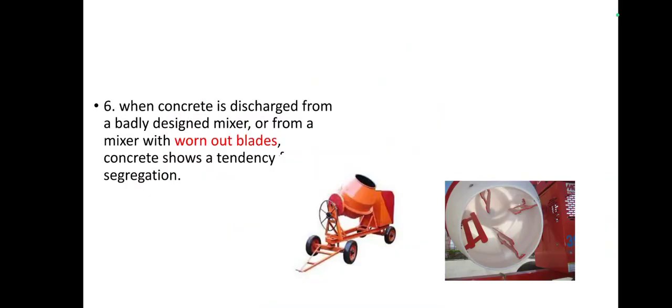And next one, when we are using a drum mixer which is too old, the blades will be somewhat blunted, so the concrete won't mix properly, and homogeneity may not be ensured.